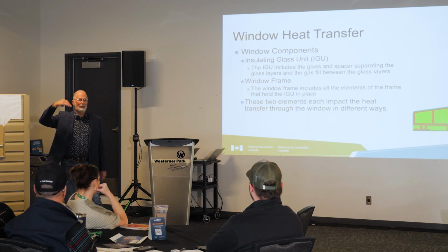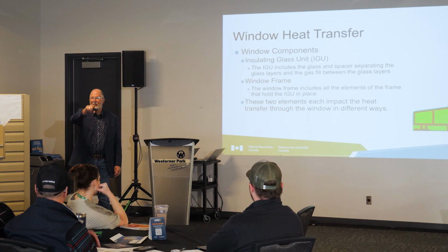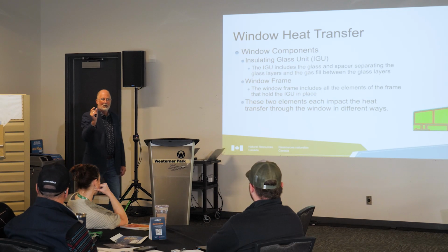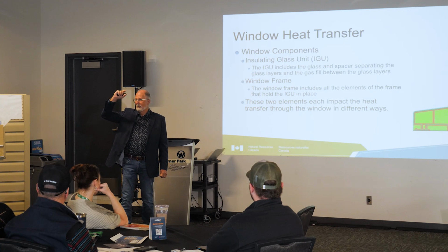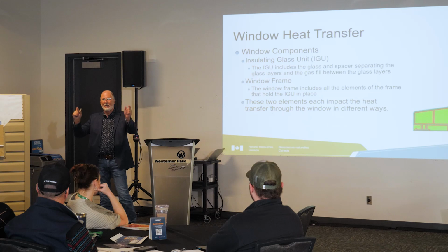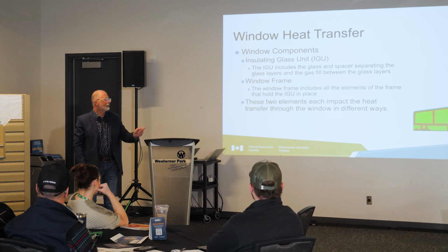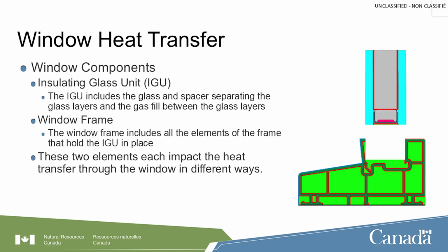It actually can be pretty high. You get a giant chunk of glass there in a triple glaze, the middle of that window could be R12. It could be super high. But as you get closer to the frame, it gets colder and colder and colder. So the frame becomes one of the most important parts because we take an average.